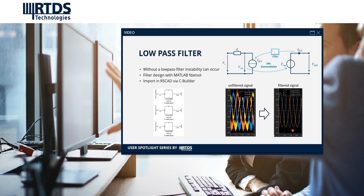The filter is designed with Matlab and then imported to RSCAD via the C builder, which is very convenient. Afterwards I get a black box with the filter characteristics that I can integrate into my RSCAD model.